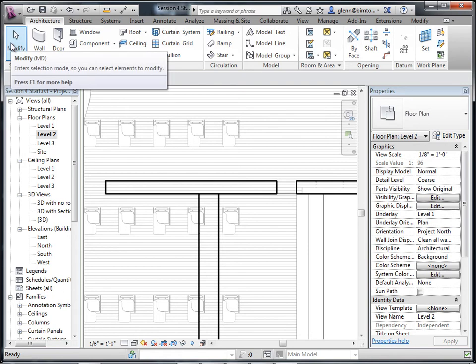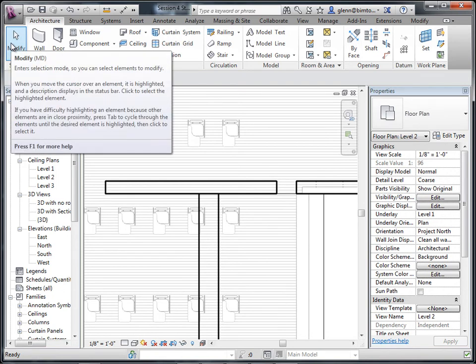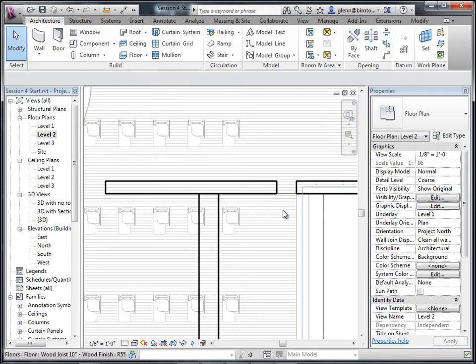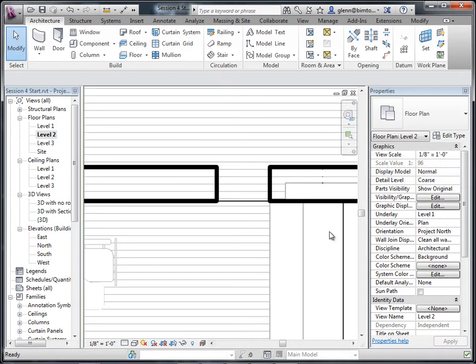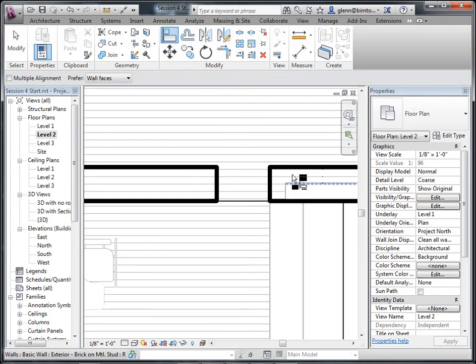Now, I went ahead and drew that as a separate wall because I don't want it to actually be joined to this wall. I'm going to actually have them be two separate walls that kind of come together at the corner because they have these different base points. Now, what I may want to do relative to this wall is I can align some things. For example, I just sort of drew that and I think I'm pretty close, but if I really want to make sure those two things line up, I might want to say let's align this and align that outer surface here to match the outer surface here. And lock those. Okay, that just makes sure that if one moves, they both move together.